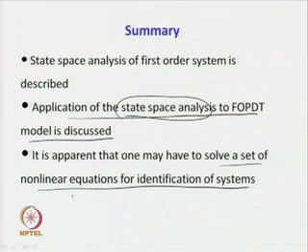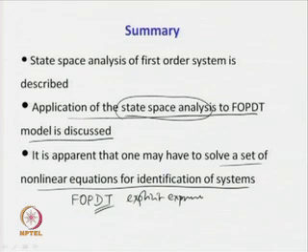This is not necessary for the first order plus dead time system. Fortunately, we can derive explicit expressions for the unknowns of the first order plus dead time model, theta and T 1, in terms of the measurements A p, p u by 2 and the knowns k and h.